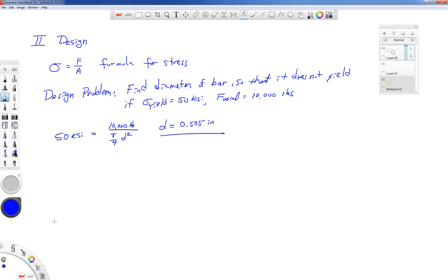So to show this variation, it's probably easiest to draw what's called a normal distribution or normal probability curve. You may know this is a bell curve. Some materials work well with different kinds of distributions, but this is one that'll suit our purposes here. And so on the vertical axis is going to be the number of tests that we've conducted. And on this bottom axis would be the strength in KSI, the yield strength in particular for this example.